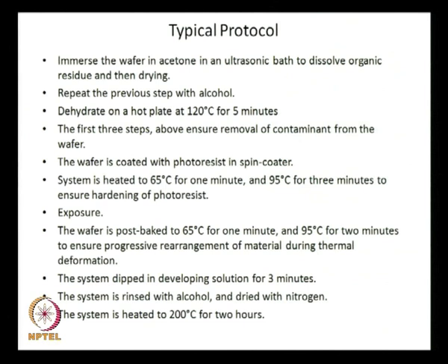So, this is a typical protocol that is followed. I mentioned that at first you have to put a mask aligner and take the exposure. Prior to that, you have to have spin coating done, but I said that particles are not allowed on the substrate surface, because if particles are sitting there on the substrate, that can disturb the spin coating process and the coating will not be uniform and there would be all kinds of problems coming up.